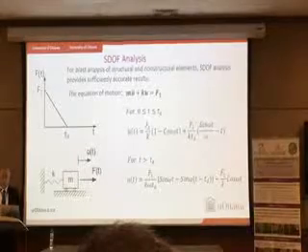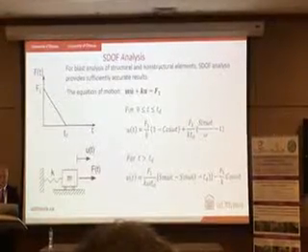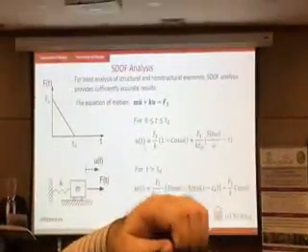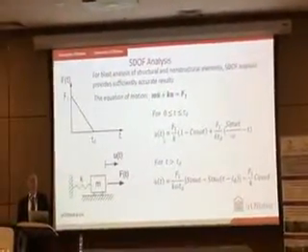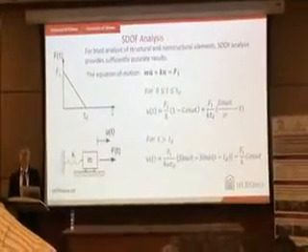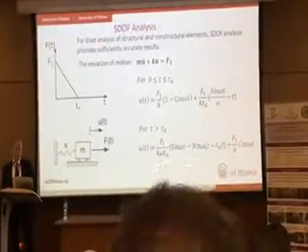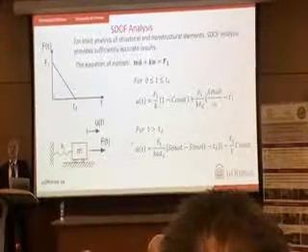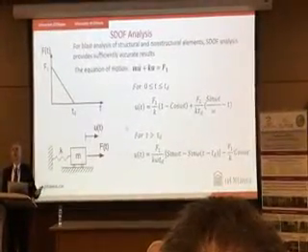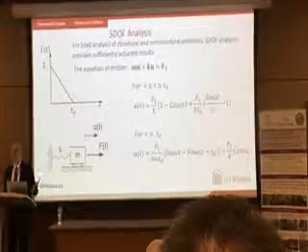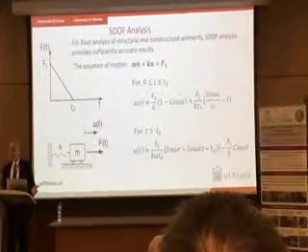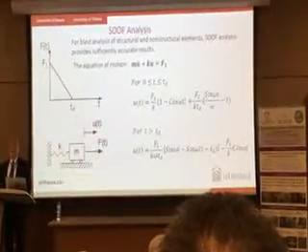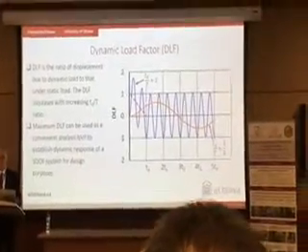I have closed form solutions. As complicated as it looks, it's very easy. You now have displacement of the building under this blast loading varying as a function of time. This is forced vibration zone, this is free vibration zone. I have two expressions. So all you have to do is plug in values. Omega is the frequency of the column or a wall. Then you get dynamic response of the single degree of freedom system.